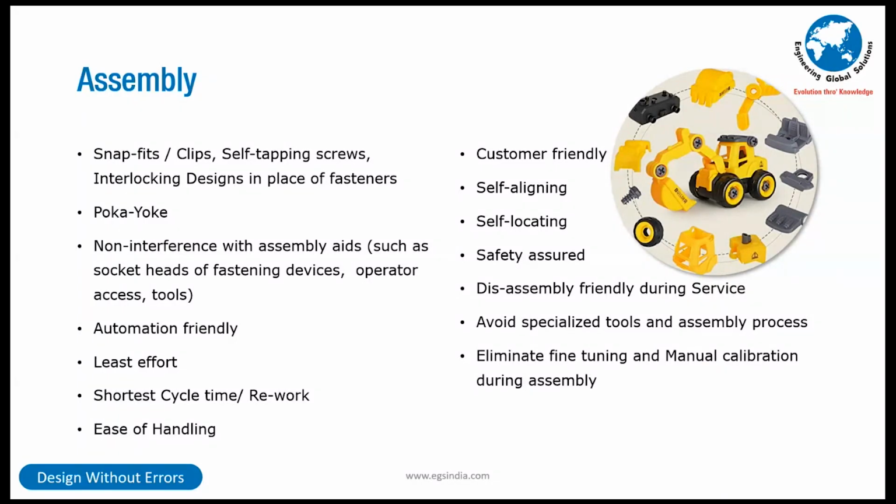Poka-yoke, you have to conditionalize it at your design stage. Absolutely. If you ask me, is design responsible for it? Absolutely, they are responsible for it. They are the drivers. The executors are the people on the manufacturing shop floor, but it comes from here. Consider the non-interference with regard to the assembly aids that the operator uses. For example, in a suspension spindle, we always give the socket head clearance on the lower ball joint assembly, primarily because you cannot otherwise turn it. Nobody is going to turn it with a spanner. There's a power tool which is going to be used,